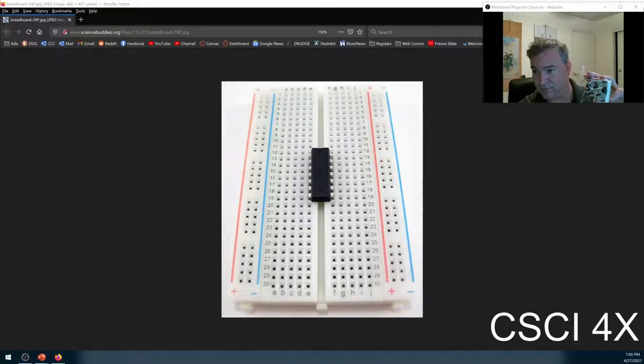I've repeated that circuit 3 times. At the very end of the LED, there is a wire running back into ground. That completes the circuit. By default the circuit is open, but if I press the button, it closes the circuit. Current flows from the hot rail through the blue wire into the button, into the resistor, into the LED, into the ground, completing the circuit, and the LED turns on.